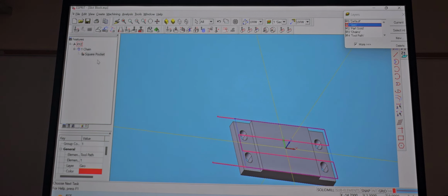So I'm gonna hit OK now. So you guys see how that was deeper and it came up, right? The toolpath. And it did that because of the depth. The original one was 125 thousandths, and I just tell it, hey, only go 5 thousandths, correct?